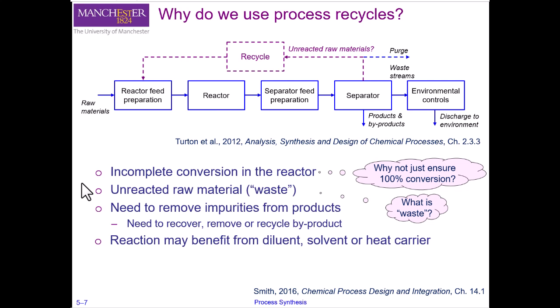Increasing conversion may also promote competing reactions or side reactions, and as such, you might reduce your yield. But the raw material and the waste associated with unreacted raw material due to low conversion is also another expense.